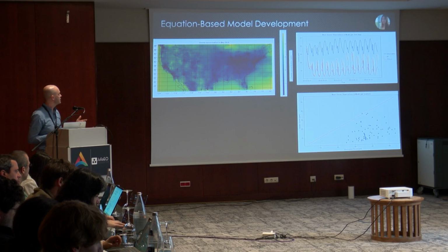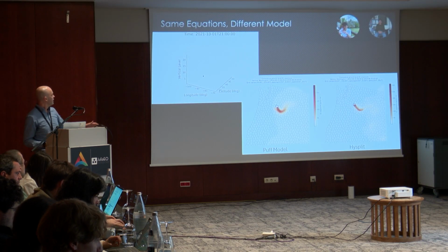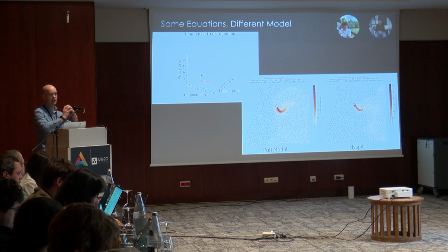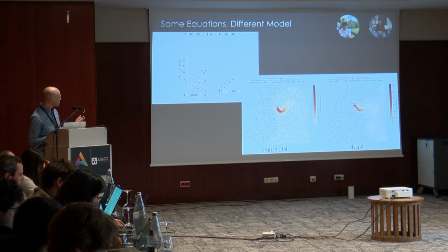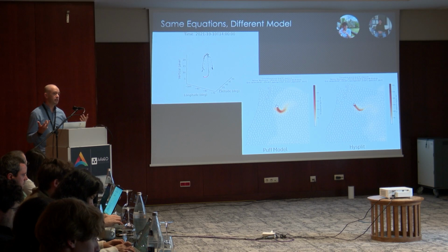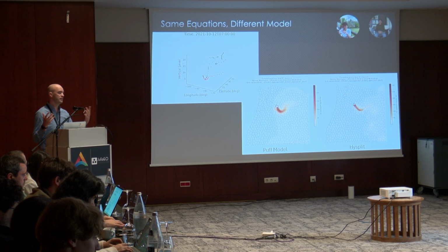Another thing that we can do is, there are different frames of reference that can be useful in this type of modeling. The one we have back here is where we split our domain into grid cells and track how things move in between the grid cells. We call that an Eulerian frame of reference. Another thing that sometimes we want to do is say our frame of reference is a packet of air or fluid and track that packet as it moves around through the atmosphere. That's called a Lagrangian frame of reference. In both cases, it's the same system of equations, but in a different form.